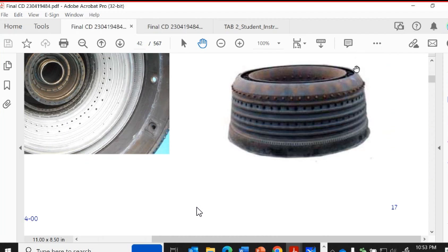The CDP air is going to come across here, hit against this ridge, but because my hole is on this side, or we'll use this one because you can see it a little bit better. As the air hits against this, instead of going up and around, I got a hole right here. So it's going to take the path of least resistance, and this is going to force the air inside my combustor.